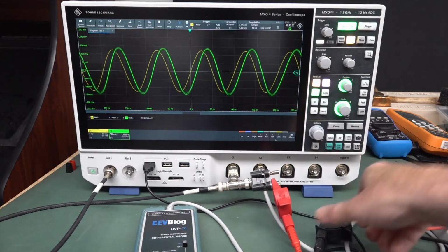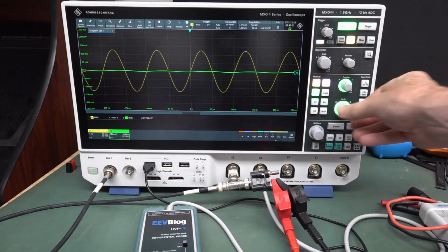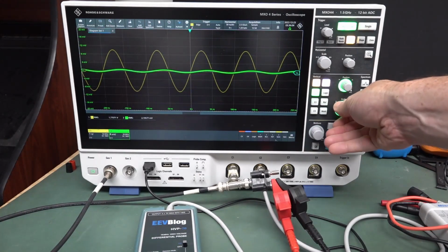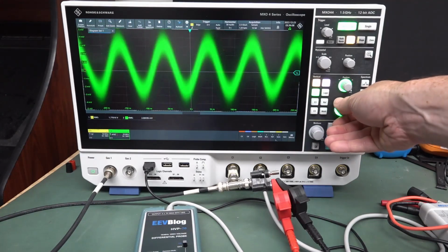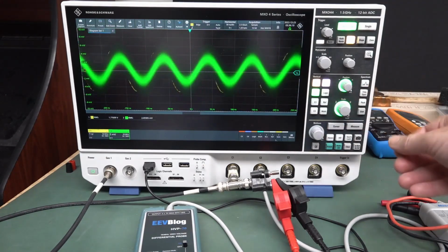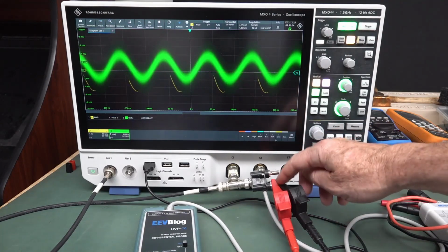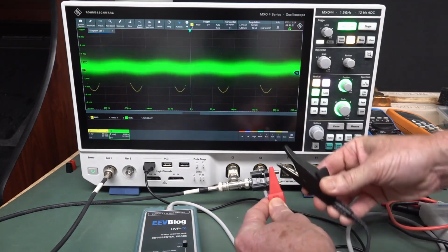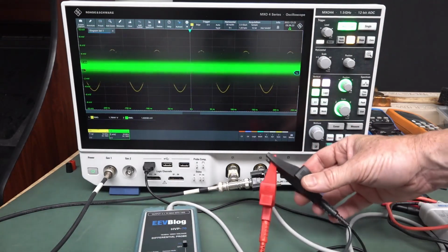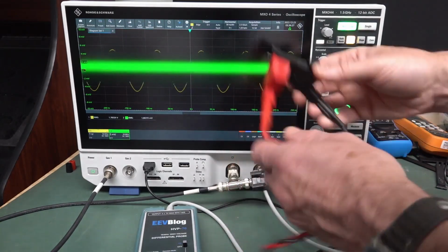But if you connect both of them like that to the same point, then bingo, we've got a really small signal. So this probe isn't perfect. It's got a common mode rejection ratio. So there you go. There's a signal being amplified even though that input is completely shorted. And you'll notice that goes away if we don't connect up to that. Okay, there's our ground there, so we've just got the inherent noise of that amplifier.